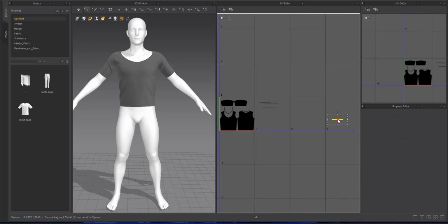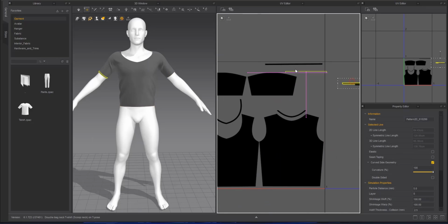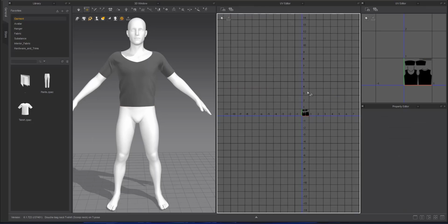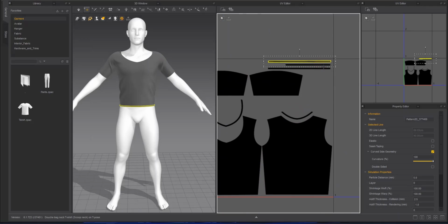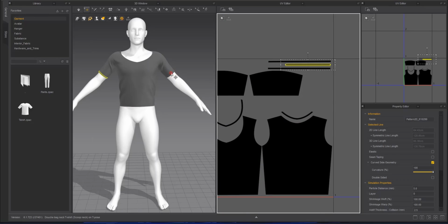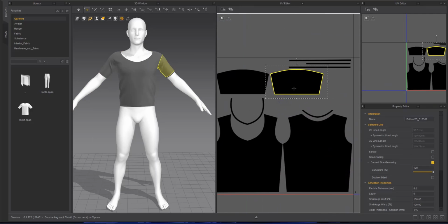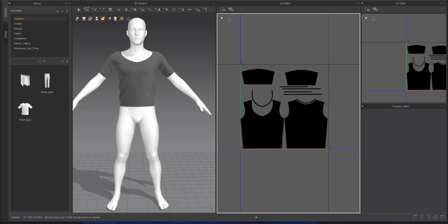You can set the unwrap type based on UDIM and set the whole clusters on 2 or more UV screens. In this case, each of the clusters will be placed in a larger size and the texture will be placed on it with higher quality. The larger the clusters, the more UV space they take up and the higher the quality of the material. Try to adjust the clusters so that they are as large as possible in UV.